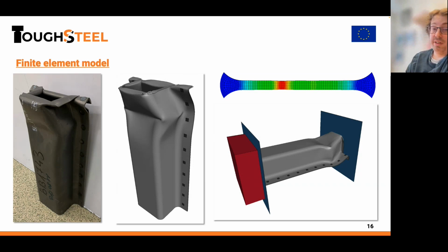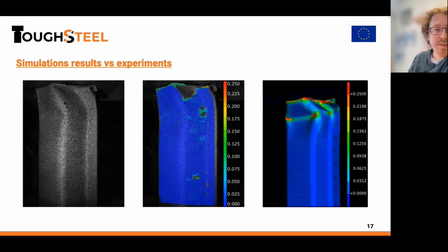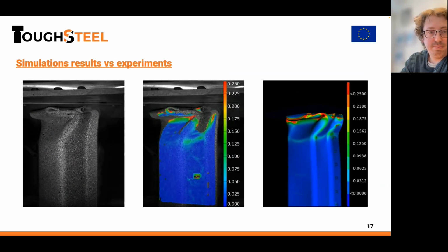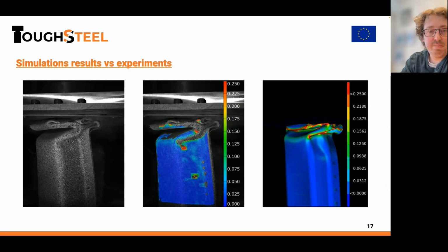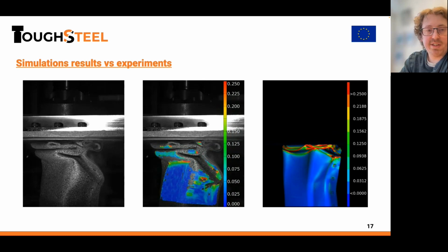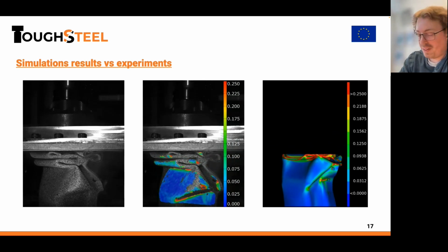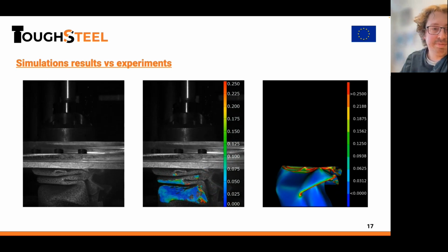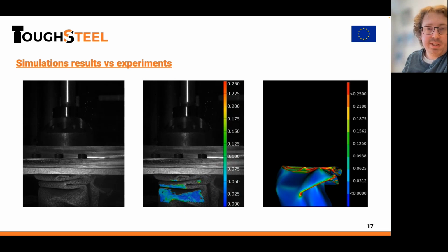And this is often nonlinear and can be highly nonlinear and very measure dependent as well. So this needs to be inverse modeled for every material still, at least with this empirical finite element damage model. And here you can see the result when we compare the 3D digital image correlation with the finite element model I made quickly. And we can see that, of course, it loses some facets because it's a complex deformation process, but we can track the deformation pretty accurately, which is nice to see.